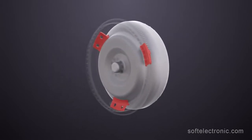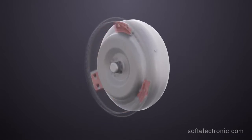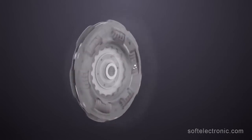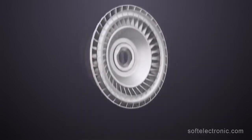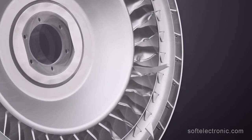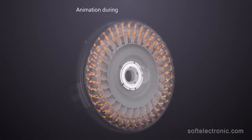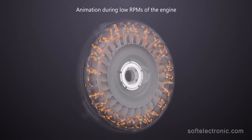Vibration and improper mounting can detach the carrier plates from the torque converter housing, which can result in serious damage. There are also cases where, due to untimely or poor repair, the damper can be disassembled and the gearbox may be blocked. Under such conditions, a turbine blade or the pump may break, which begins to circulate freely in the fluid flow. This can seriously damage the components of the torque converter. If there's a problem with the one-way stator bearing, this can have a serious negative effect on the flow control between the pump and the turbine.